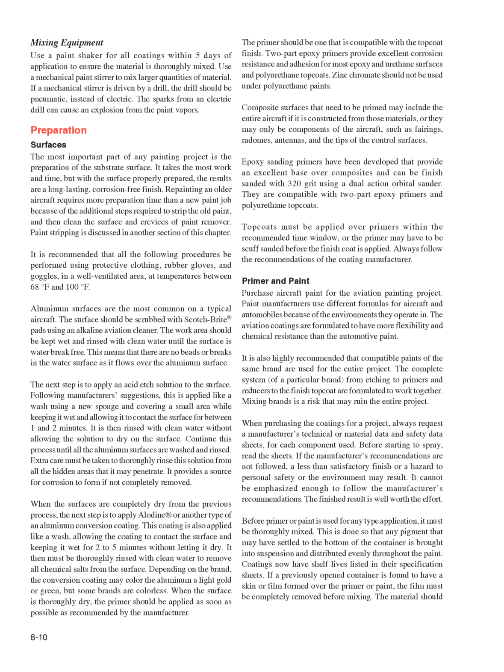The primer should be one that is compatible with the topcoat finish. Two-part epoxy primers provide excellent corrosion resistance and adhesion for most epoxy and urethane surfaces and polyurethane topcoats. Zinc chromate should not be used under polyurethane paints.